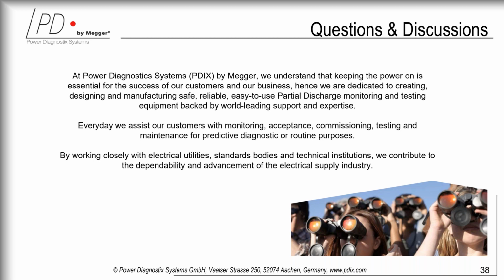So whenever such a disturbance pulse appears in the system, a so-called gate is opened on the measurement pulse and is then rejecting this disturbance pulse from the measurement pulse. It's a very simple analog circuit, but that works for disturbance signals with, let's say, relatively low repetition rate. If we see disturbance signals of very high repetition rate, then we go into a different spectra of the measurement. So the instrument offers different ways to get rid of these external disturbances.